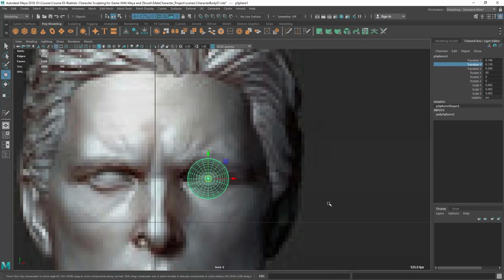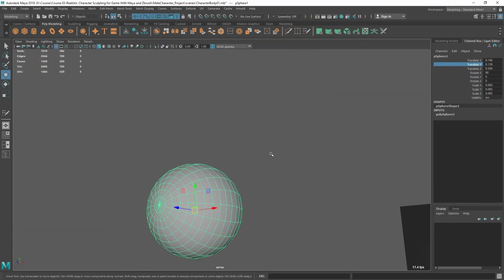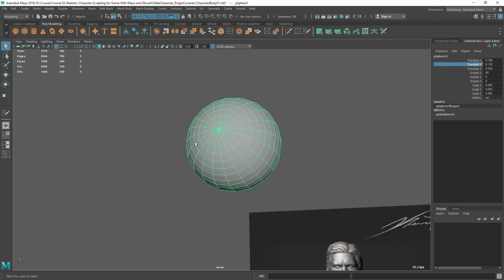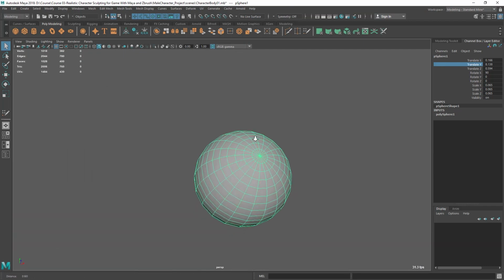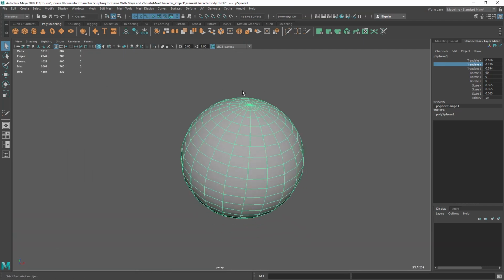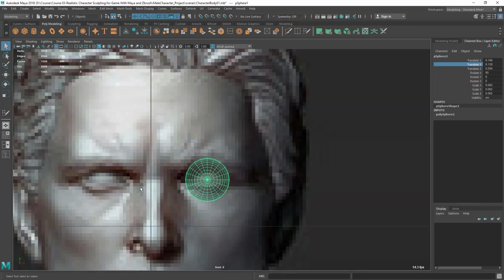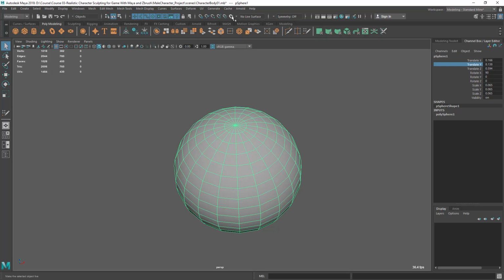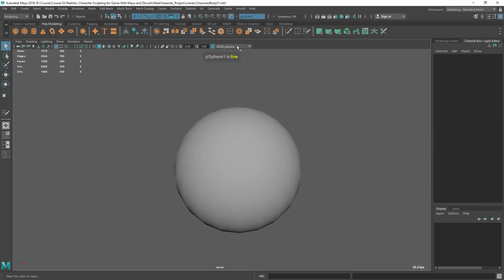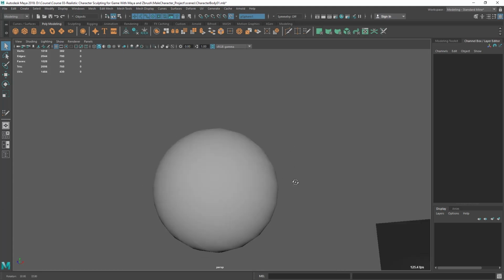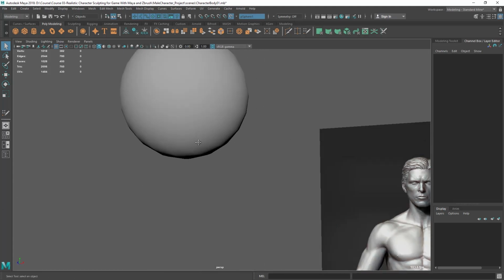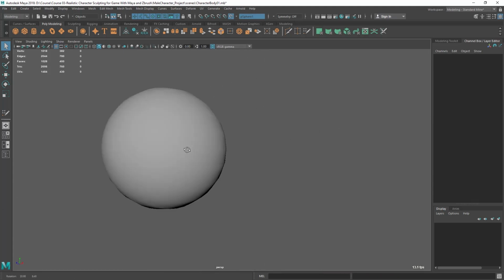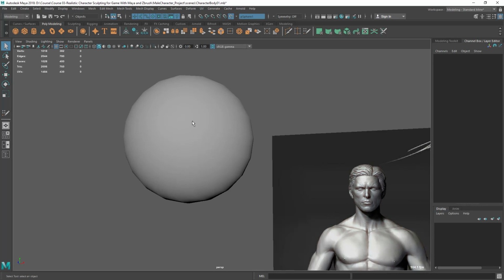Once I have put the eyeball there, then I'm going to model that surrounding skin, and it should be a little offset kind of thing, the skin, and then I can see the depth of the skin around the eye here. So I'm going to make it live. I have selected it and I just clicked here. So now my model is a live object. When an object is live, I cannot select it anymore, but I can create something on top of this.